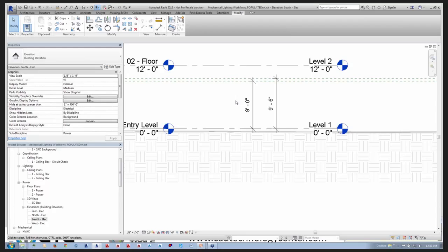And if you didn't want that to happen, what you might want to do is go back and create a clearance box family and assign that family to a panel clearance subcategory, and then copy that family and assign this new copy to a lighting clearance subcategory, and so on and so forth. If you want to bring it to a more granularized approach, that might be how you would do that.